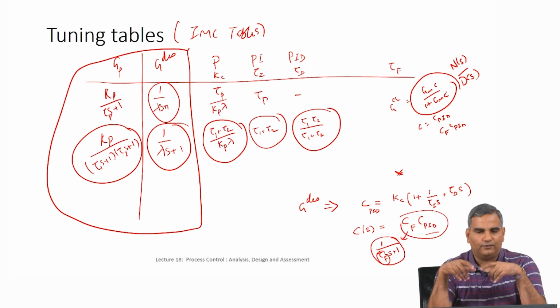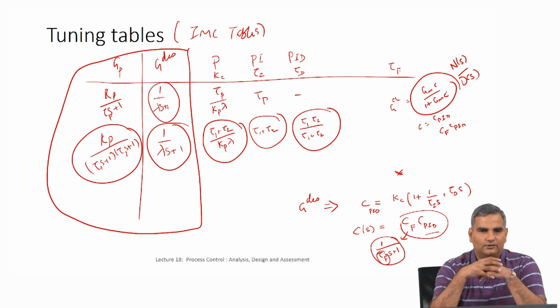Then I said before we do that, because this partial fraction idea is not going to be enough for us to understand this, I introduced the notion of the Routh table. So here I said if I have a denominator polynomial which has coefficients which are all constants, then you can actually get the root resolved form and then understand stability.